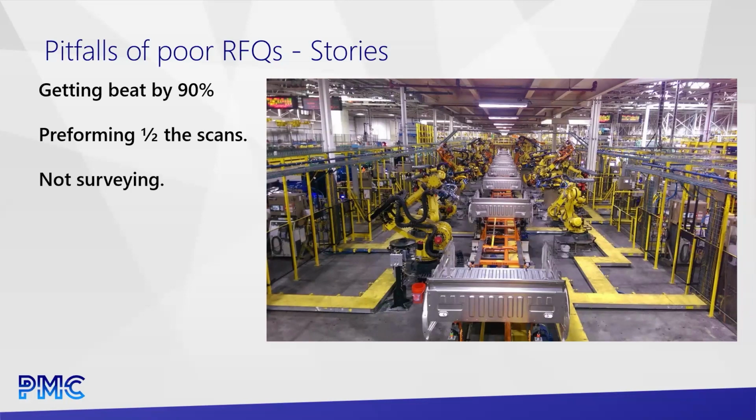And then you start adding the next scan and the next scan, and you start chaining these together through the space. Well, if each one is off by even 1/100th of a degree out of level, all of a sudden, by the time you get to the end, your entire site is going up a hill, and your floor can deviate again by feet. This is not workable data. Modelers will have an almost impossible time dealing with it.